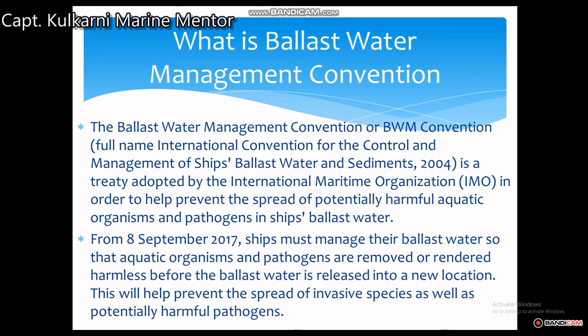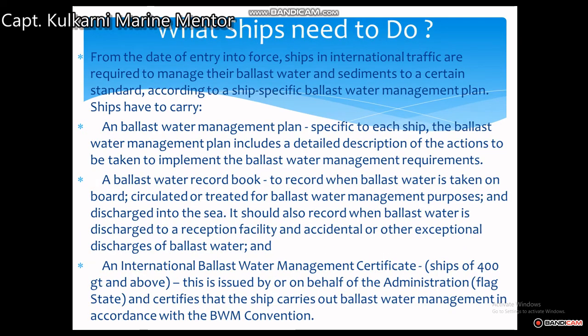What a ship needs to do from the date of entry into force, which is what we are talking about in 2017: ships in international traffic are required to manage their ballast water and sediments to a certain standard, according to a ship-specific ballast water management plan. Now, does a ship need to carry a ballast water management plan? This plan has to be accepted by the flag state.